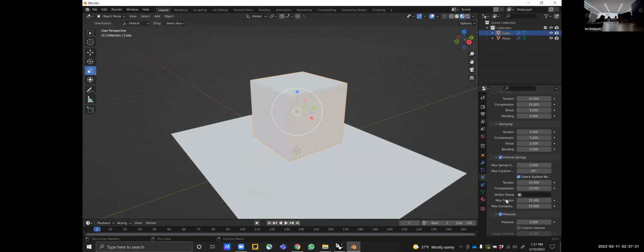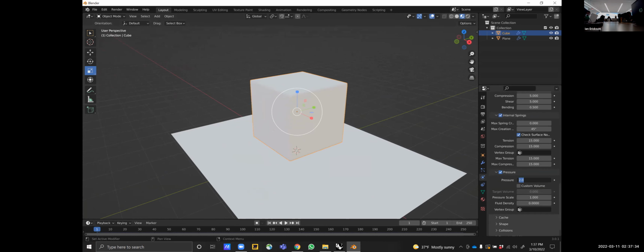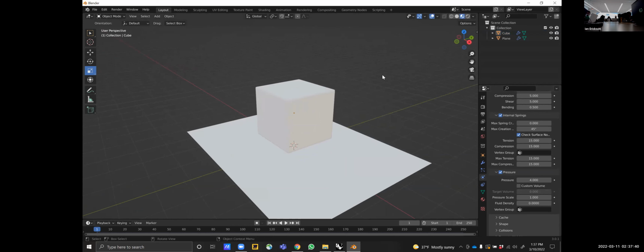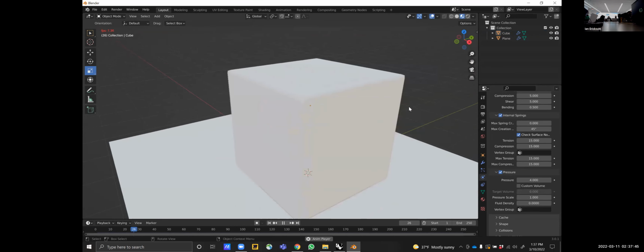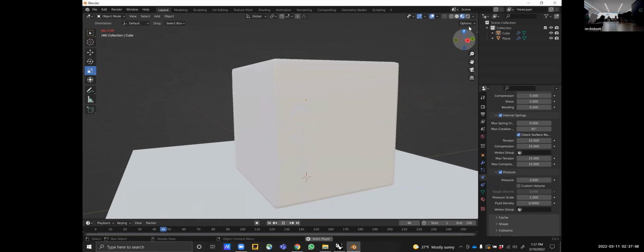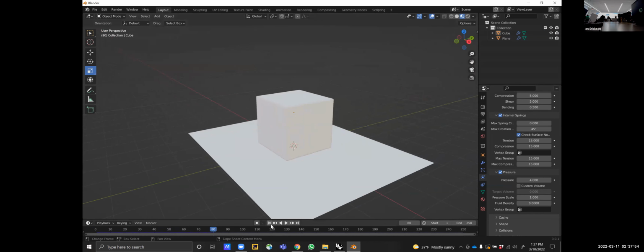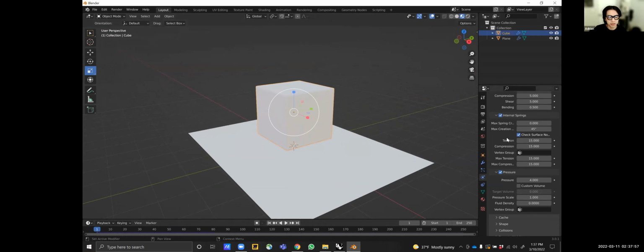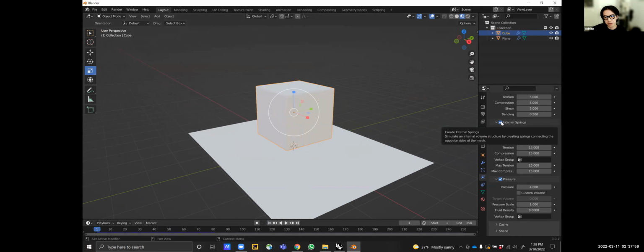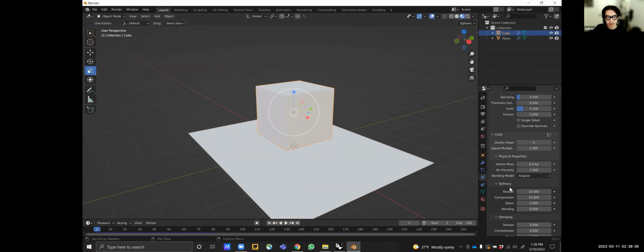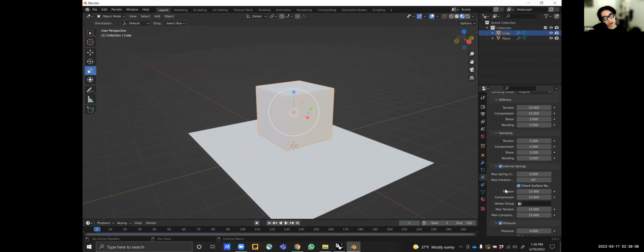When you run that with a lot of pressure applied and a complex object, the surface will begin to ripple as if there are actual cables inside. You see how it's just retaining its shape as is. That's a useful command if you don't want it to get too floppy. If you want it to fall without changing, right? Because by default, objects, if you animate them, won't fall. But if you give them a cloth property and internal springs, then they'll fall.